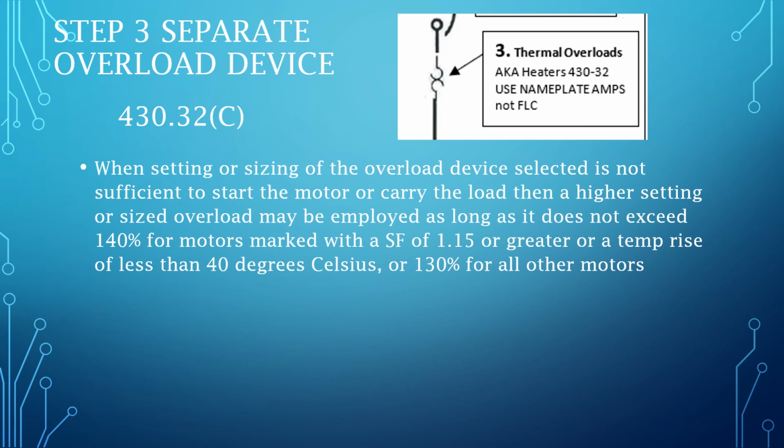A 20 amp motor, if it's drawing 20 amps when that motor is running, if we start that motor from a dead stop with a load attached to it, that motor may draw 60 or 70 amps for a split second, or for up to a second.